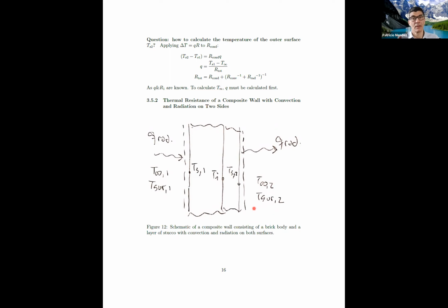resistance. If I have a parallel circuit, for example, where the heat losses by convection are much higher than the heat losses by radiation, then it is the smallest value of resistance that rules. It's the smallest value of resistance because it's the highest amount of heat shortcutting through that path, right? We have to keep this in mind.